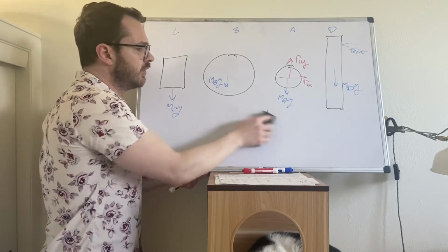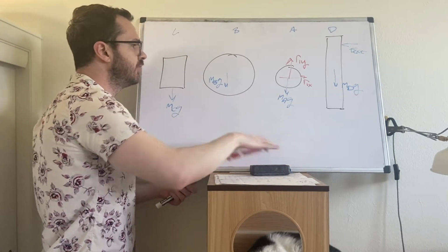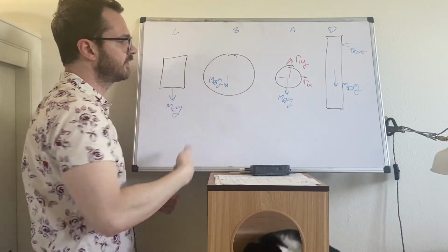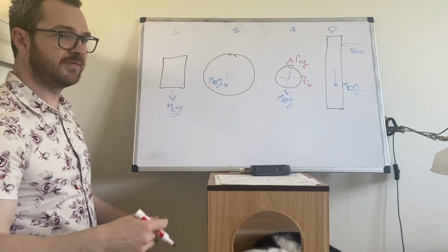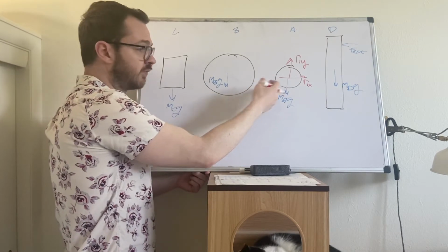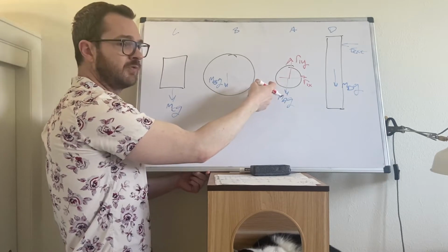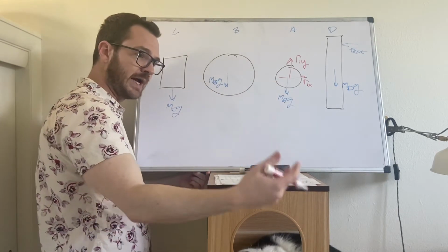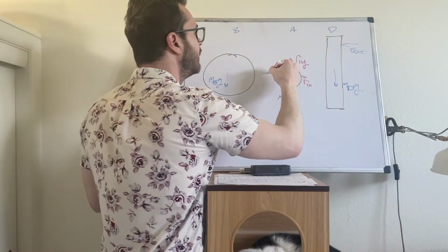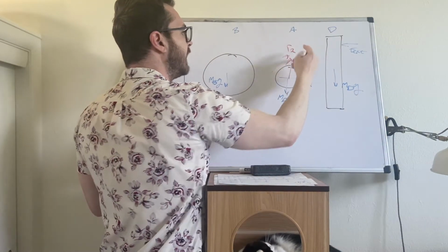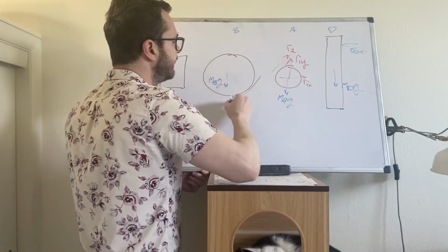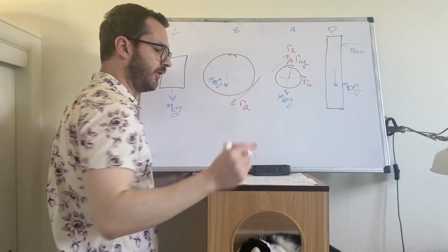So what we're going to do, we just need to model the transmission force between these two discs, and I'm going to label it as if it's just another reaction force, because remember, this is in fact a joint, right? There's even a constraint between these, which means that there has to be a reaction force to enforce the constraint. So I called that one R2. I did it positive or up and right on A, and I did it down left on B. Okay.